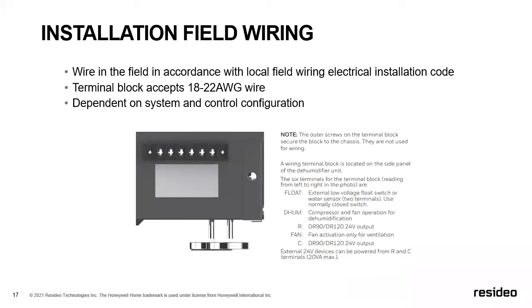I've had some guys leave the jumper in, not think about it, and then put their float switch in, and of course, maybe have a float scenario that should have tripped and they forgot to remove the jumper. So remove the jumper on the float terminal.